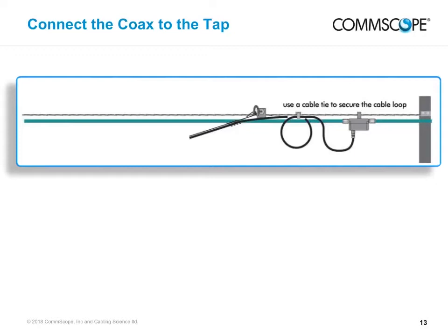to reconnectorize the cable. Store this cable by forming a loop of about 6 inches or 15 centimeters in diameter. Make sure the diameter of the loop is no smaller than 10 times the outer diameter of the cable. Use cable ties to form and secure the loop to the span. Attach an identification tag to the cable.